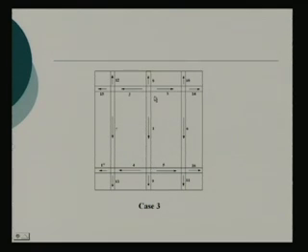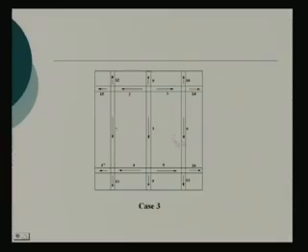middle first, then 2, 3, 4, 5. That means what? This part is getting stiffened. You see, the central is welded and 2 transverses are welded. So, the central part is getting rigid, and gradually that is progressing outwards. So, that has been done.